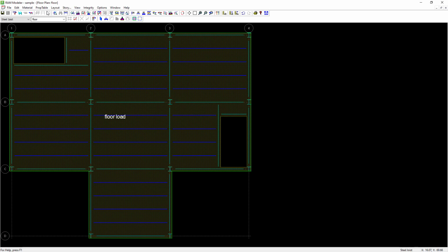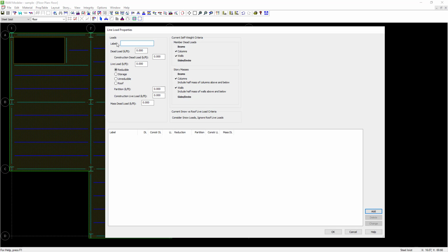And then the other thing that I'm going to do is come back here and define a line load, because around these stairwells we're going to maybe put a masonry load. I'm going to say 0.8 kips per foot. Really, these aren't there in the non-composite condition. I could leave this blank. I could put it in as 0.8.